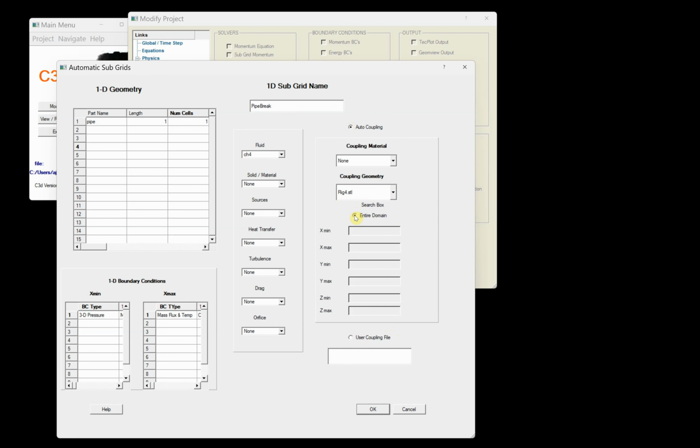For now, let's pick the entire domain. We need to modify that so that it doesn't come off of anywhere. We want to restrict it to a spherical region. Well, actually, let's do it this way. Let's go from minus 30 to 30 in the y direction, minus 30 to 30, and in the z direction, let's go from 30 to 80. And that'll create a box that contains the line source.